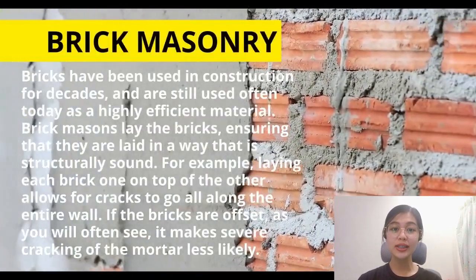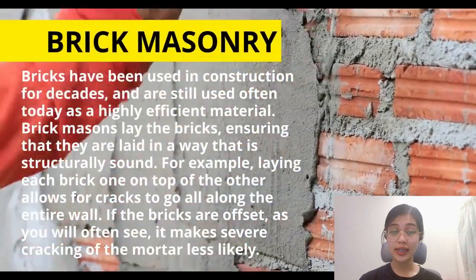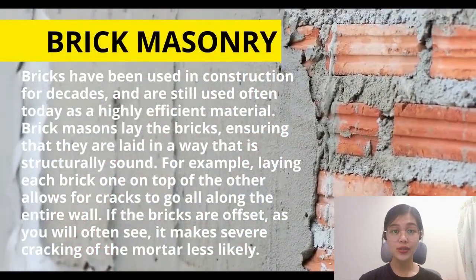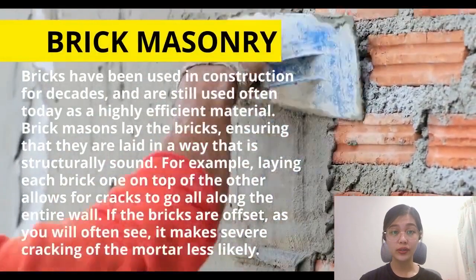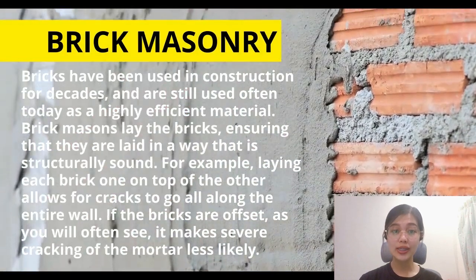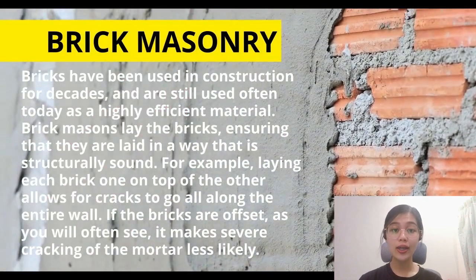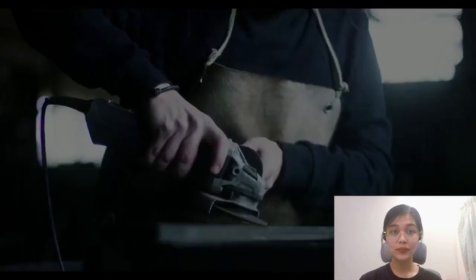Brickmanship. Bricks have been used in construction for decades and are still used often today as a highly efficient material. Brick masons lay the bricks, ensuring that they are laid in a way which is structurally sound. For example, laying each brick on top of one another allows the cracks to go along the entire wall. If the bricks are offset, as you see often, it makes severe cracking of the mortar less likely.